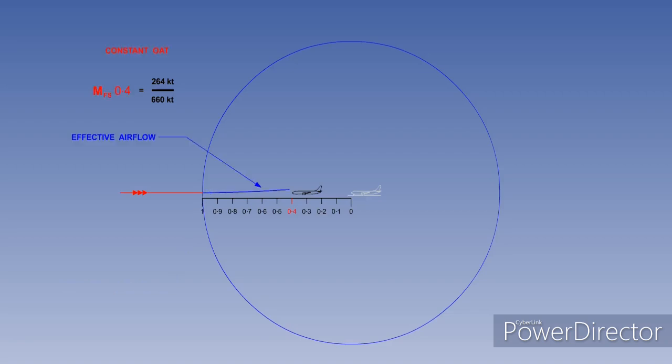You can see that as soon as the pressure wave passes over the air, it starts to upwash. The higher the Mach number, the closer the aircraft is to the leading pressure wave, and consequently, the air has to upwash through a greater angle. You learned during your study of stalling that this will cause CLmax to decrease. Hence, stall speed will increase. The effect of this change will be discussed in detail later.